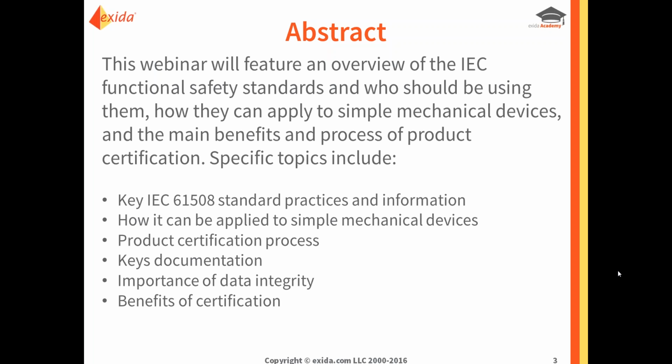So today we are going to talk about IEC 61508, what's in the standard, who the standard was meant for, how to apply the concepts to simple mechanical devices, importance of data integrity, product certification process, key documentations, and the benefits of certification.